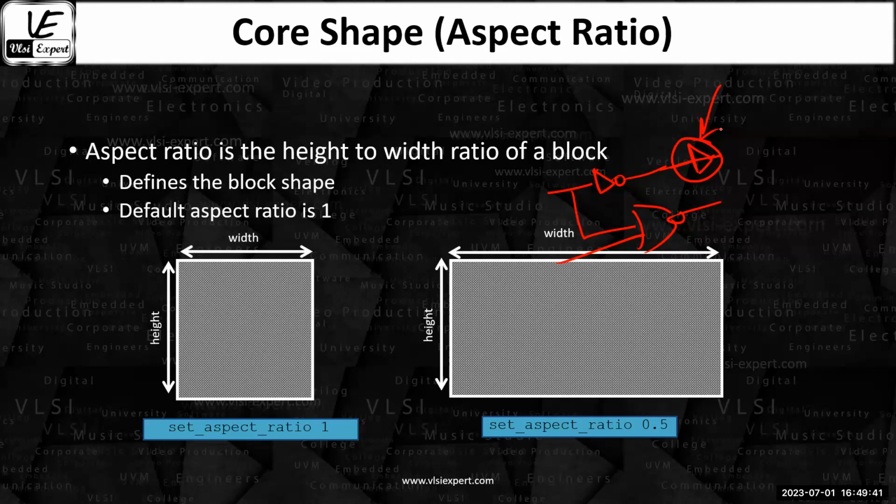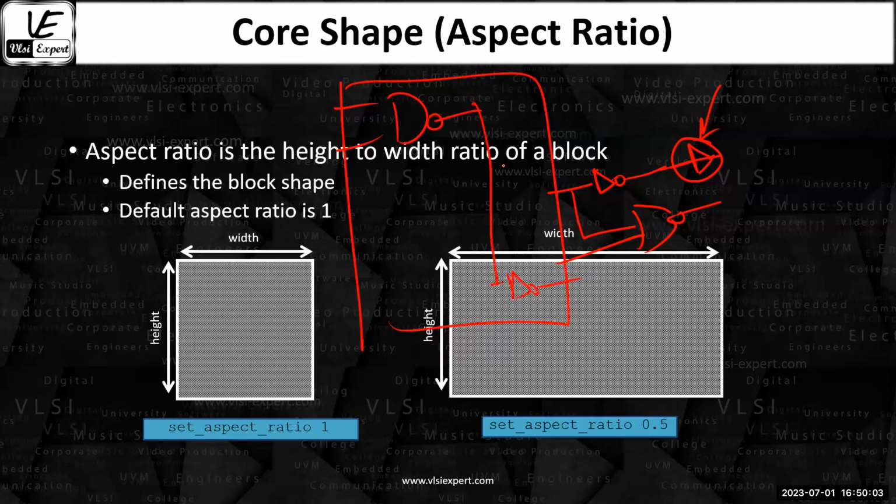Second thing is, during the logic synthesis, even when you have done the floor plan aware synthesis, you assumed it. Okay, in the floor plan aware synthesis, this is my floor plan. There's going to be an AND gate here. There's going to be one inverter here. And this is going to be my delay of wire. But there is a possibility that when you actually decide where exactly my wire is going to be, you would come to know the delay is more.